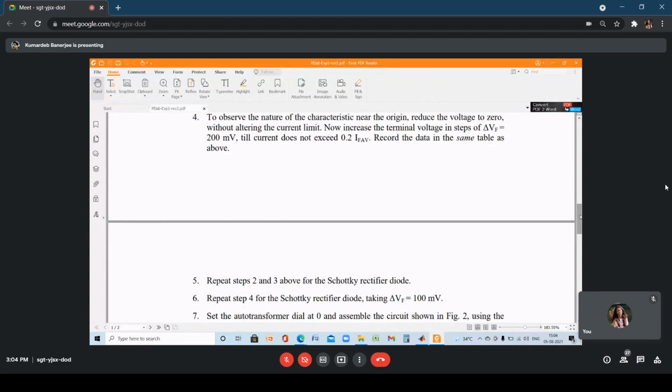So you find out the X value of that cutting point, and the corresponding voltage that ensures cutting. Clear? So this is one part of the experiment. And what is the second part? The second part is to present all this data in tabular form, and so on. Clear? Now, given this data, we'll find out from the graph what is my V gamma, right?